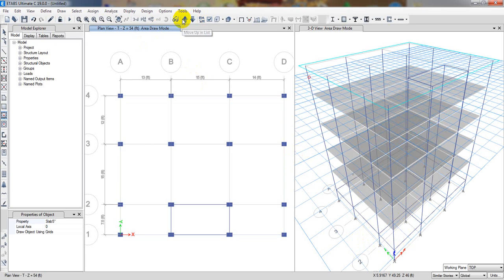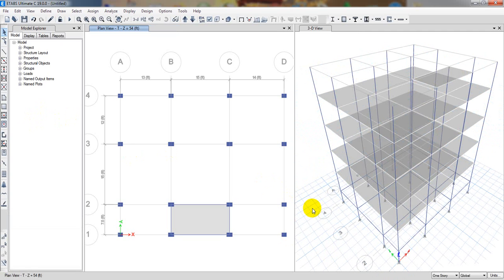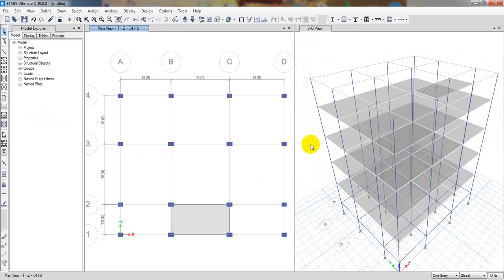Now I'll click here to go to the top one, and here I'll click on Storey, and I'll draw a slab here. So see that it's okay now, and if I escape that, now we have to delete the extra things from here. So for that I will click here, and if I delete, it's not deleting actually, so I have to simply select that one and delete manually from here. For that one also, I have to select whichever portion is not required.